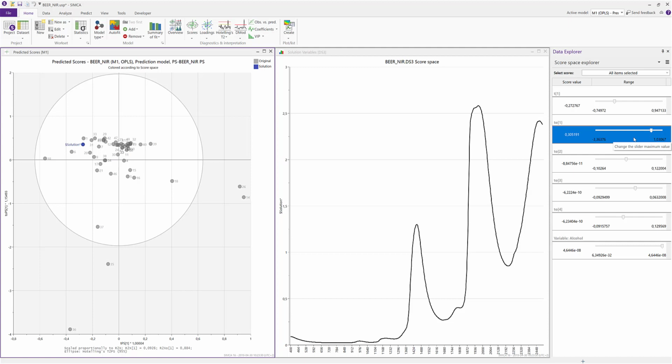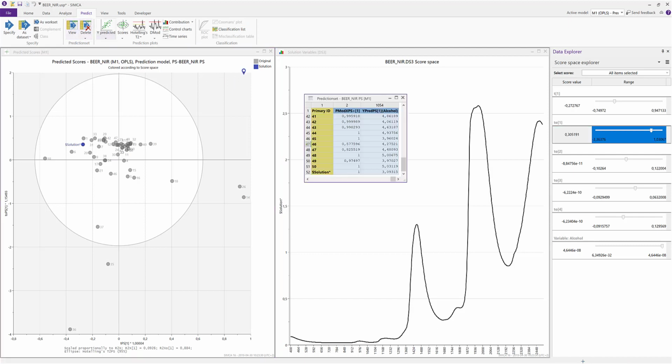If you have a predictive model, a PLS or an OPLS as in this case, you can, together with your input variable profile, also get the predicted output value for any point in the score plot, and thus immediately seeing the outcome of an imaginary point. So if I open up the list, I have the predicted value down in the corner. So whenever I click in this point in the plot, the corresponding predicted value will appear.